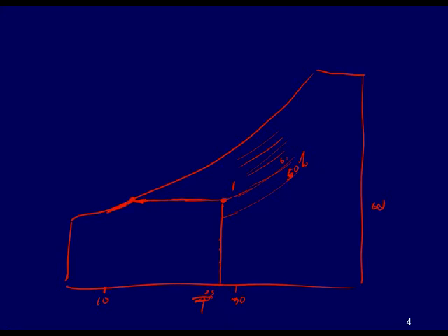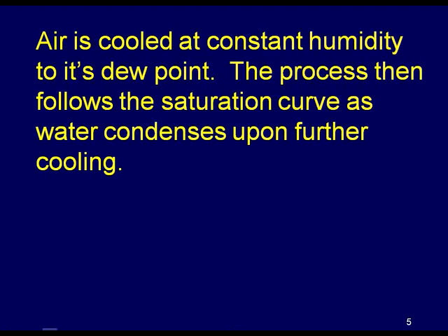So omega, the absolute amount of water in the air, drops until we get to the final outlet temperature, which was specified at 10 degrees C. That's the path you typically take: cool to saturation and then follow the saturation line down to the final temperature. And that's for humid air, such as we have along the Gulf Coast.